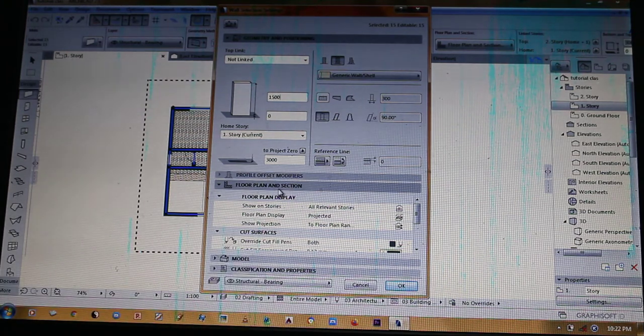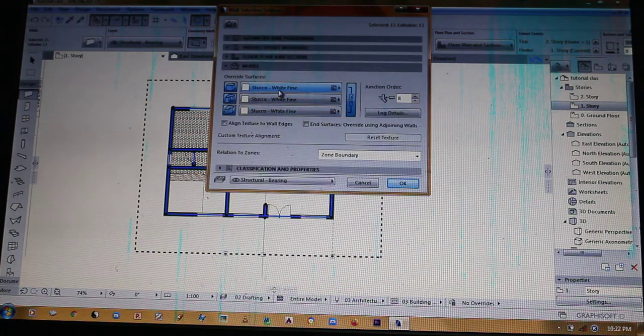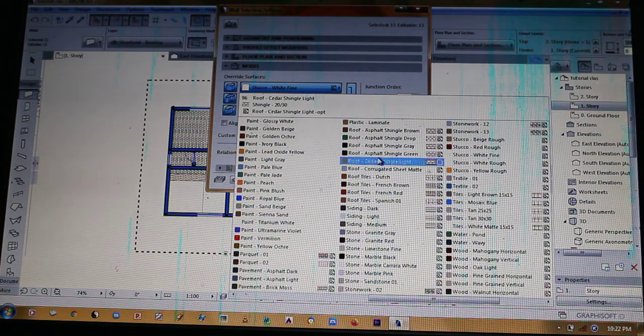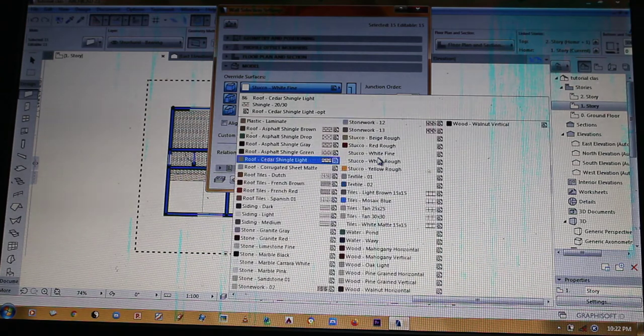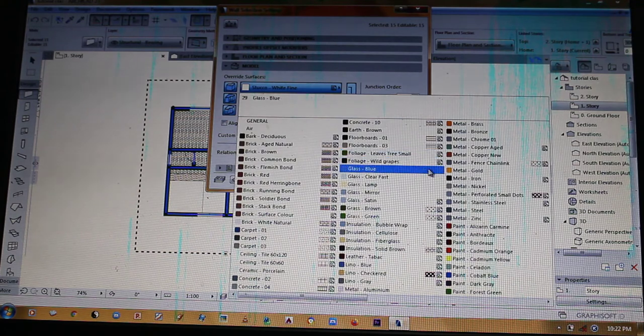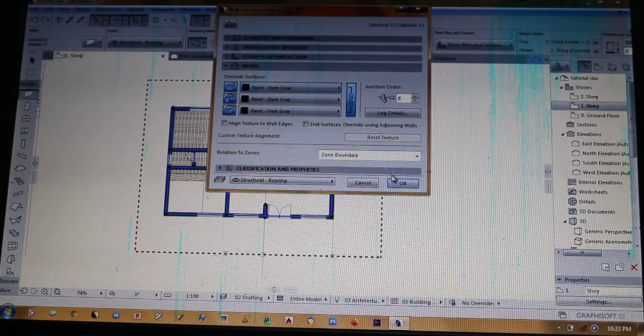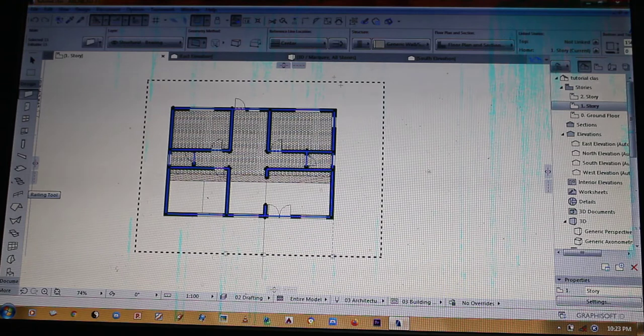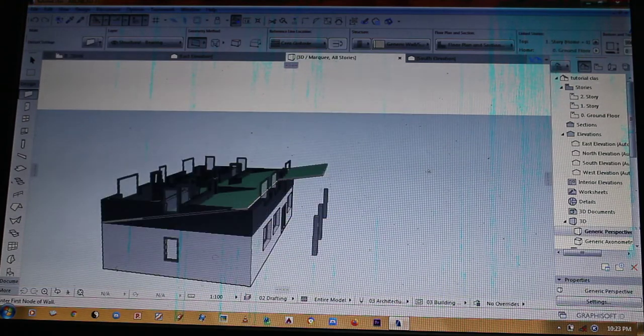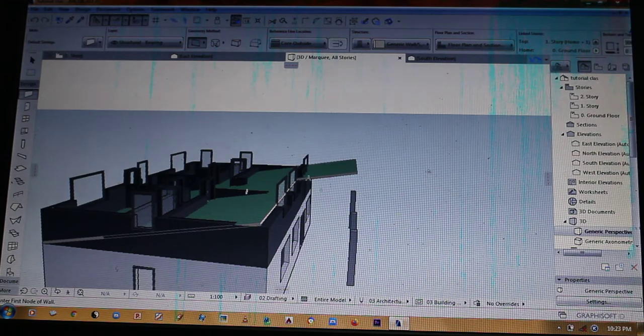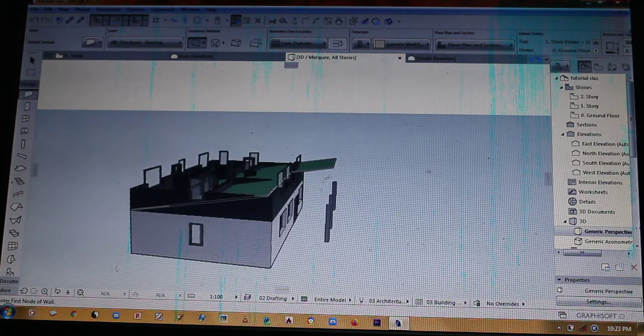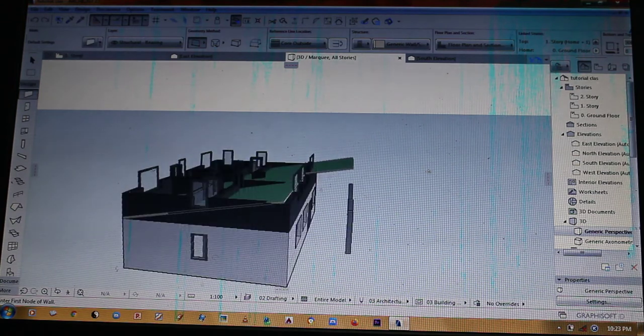And then in the model I also use a different color. The color that I really like to use is gray. Here's my gray, dark gray. Let's use this dark gray, and then I link them and I hit OK. If I hit OK and then I go to selection marquee, you will clearly see that I have a different type of wall on top, which is a parapet, and the other objects like doors and windows are still there. So I will go back to my story,